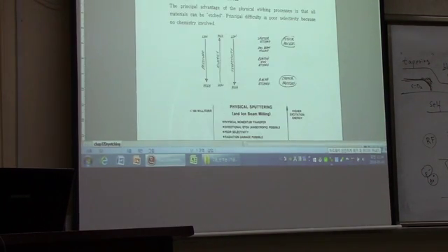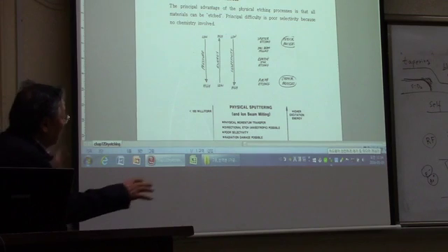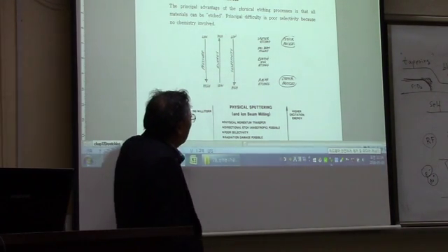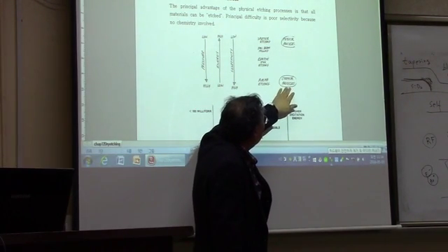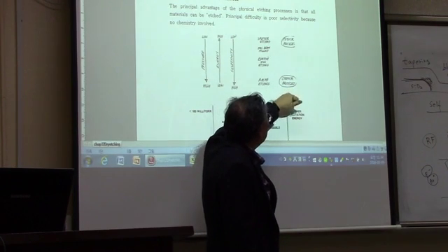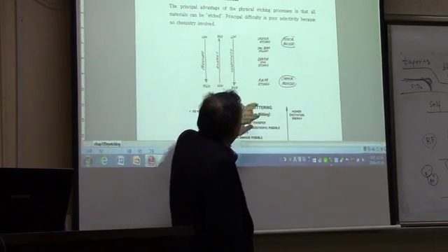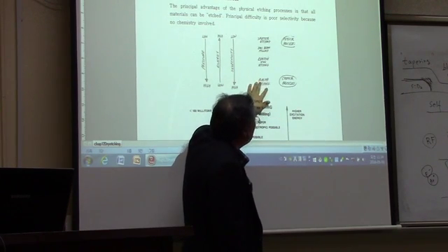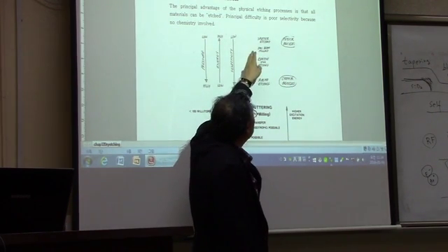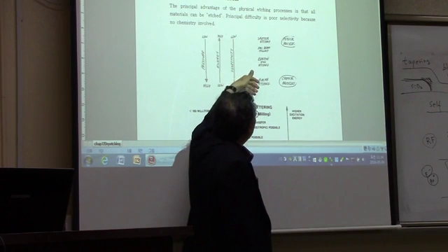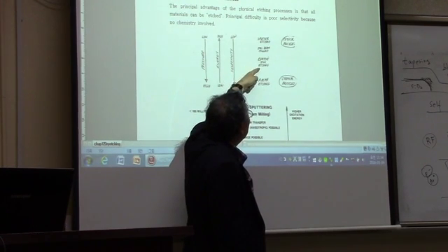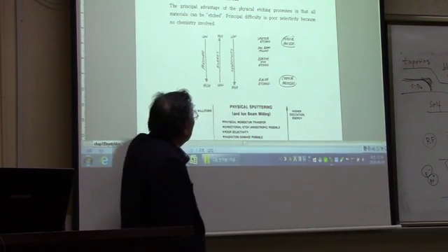And this is another way to look at the different dry etching techniques. We have a chemical process at one end, and at the other end, a physical process. For the chemical process, we have plasma etching, and for the physical process, sputter etching, and in between we have RIE and milling.